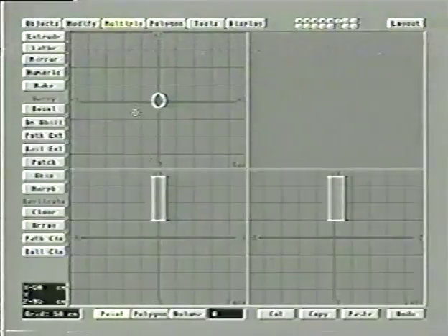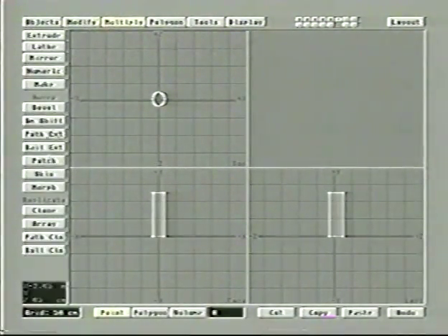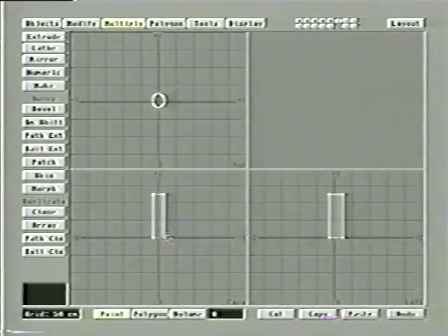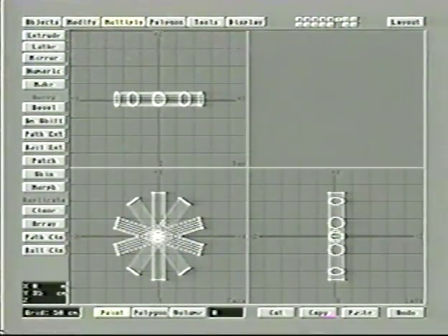Also, if we had the object in too close, let me undo what we just did and move it down a little bit here. I'm going to do a very similar thing. We'll do a clone. But you notice because the object was set right here, since there was no offset whatsoever, it didn't move it that far. So sometimes you'll need to undo your clone, move the object up, then redo it for that to work.